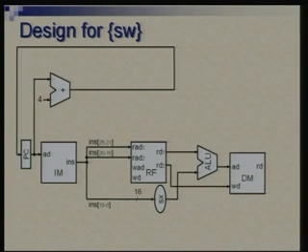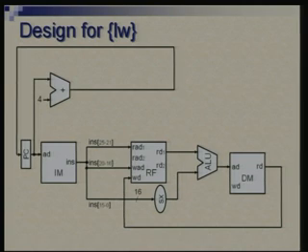All right, so the address is formed by adding one register content and 16 bits as an offset coming from the instruction. Okay. Next we have a portion of the data path which will take care of LW if that was the only instruction.